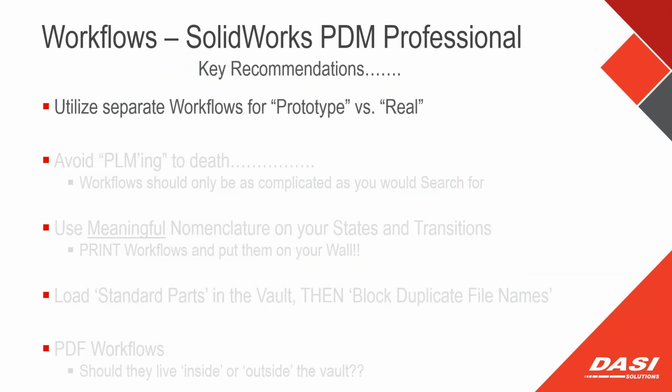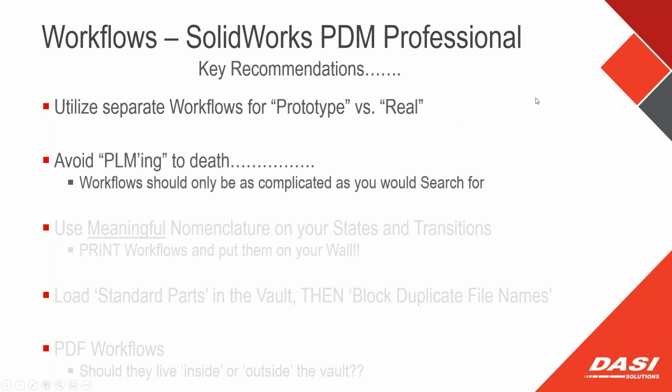So just for the workflows part of this, I wanted to recap because that was a lot of information very quickly. We want to consider using separate workflows for files that are real versus maybe not quite real yet, or just concept. Avoid too many states. You really want to find states that are milestones that are real and important to you. Don't add too much in the beginning. They're very difficult to remove. If a file has ever been in those states, you put them off to the side. It doesn't really impact the functionality, but they do have to sit in those workflows, though not connected by transitions, in perpetuity. So that's going to be there forever.